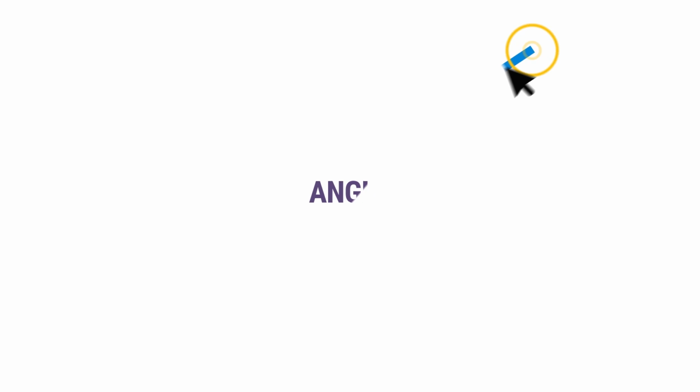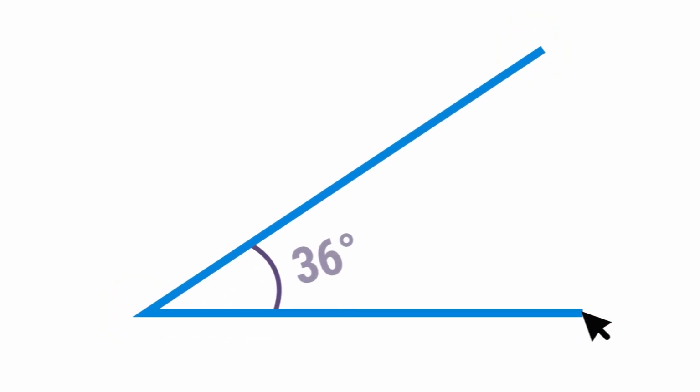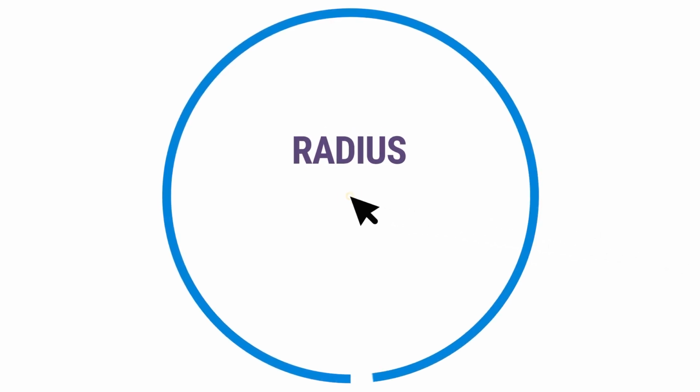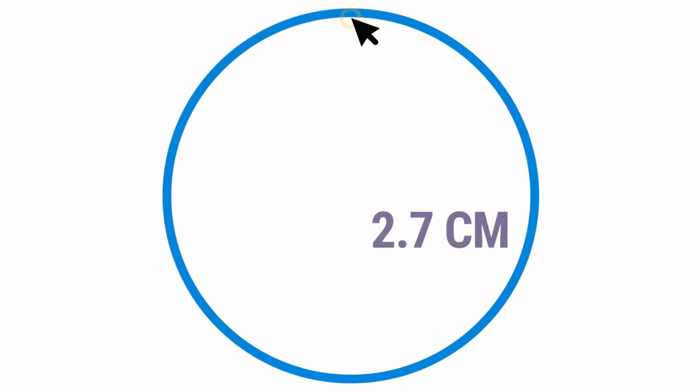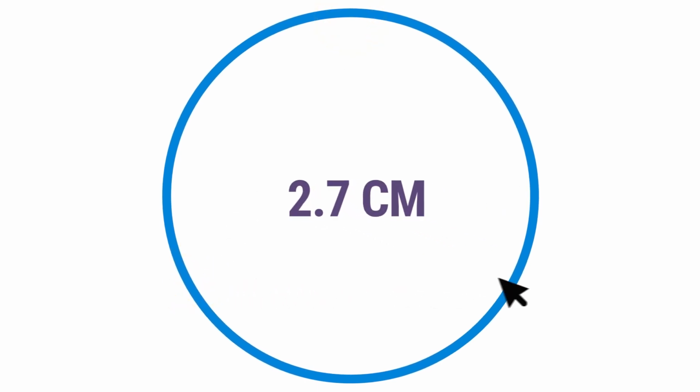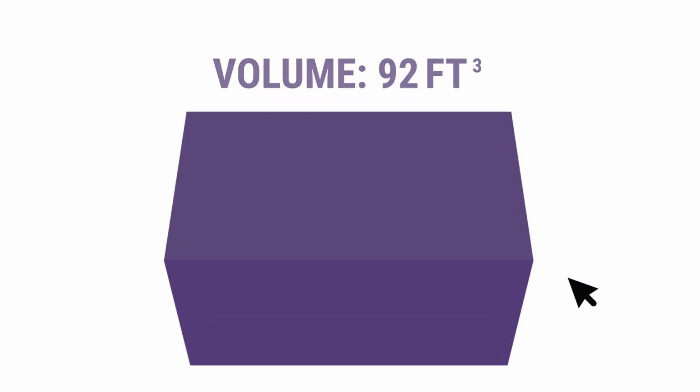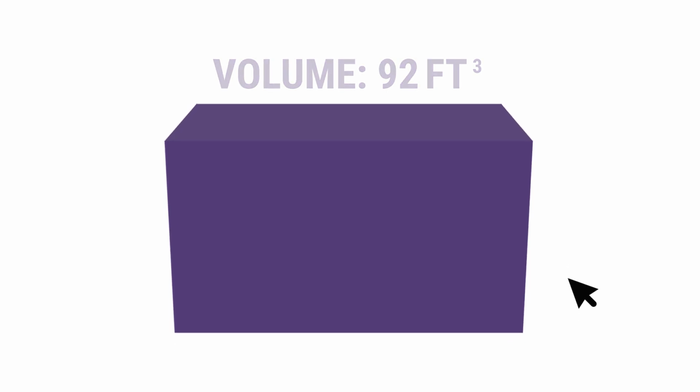Angle. Get the angle created when you click across 3 points. Radius. Find the radius of an area, either from the center point or by clicking on 3 points on a circle for accuracy. Volume. Find volume using the area selected and a defined depth in the properties, selecting points the same way you would an area measurement.